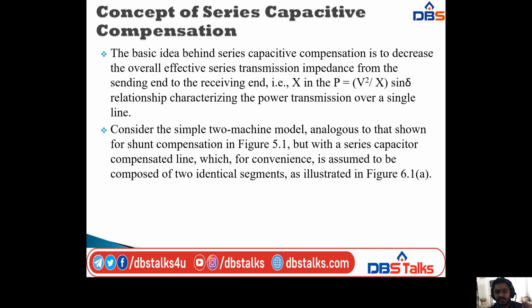In the previous chapter we discussed the concept of shunt reactive compensation, and now in this chapter I am going to discuss the concept of series capacitive compensation. The basic idea behind series capacitive compensation is to decrease the overall effective series transmission impedance from the sending end to the receiving end.